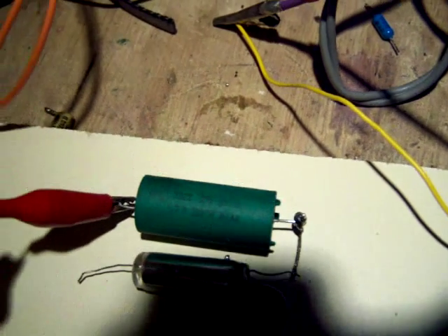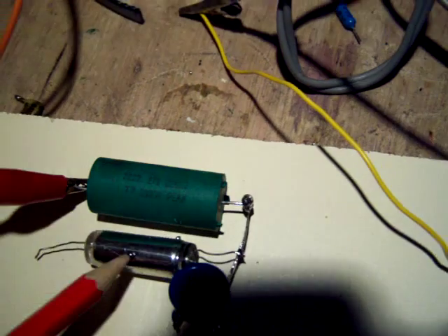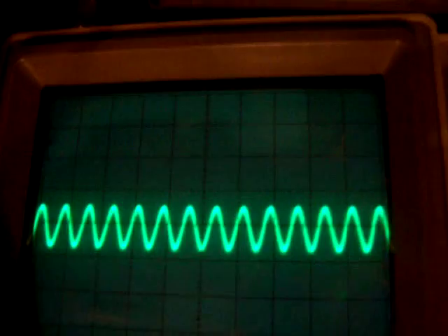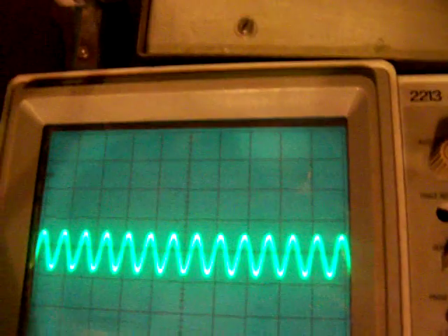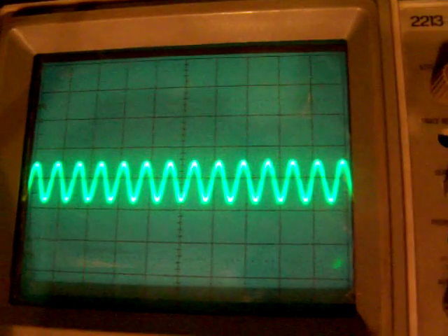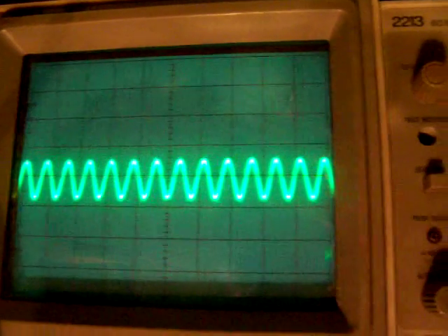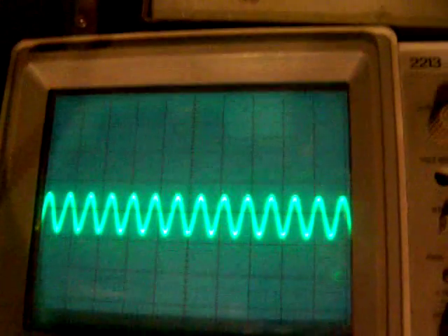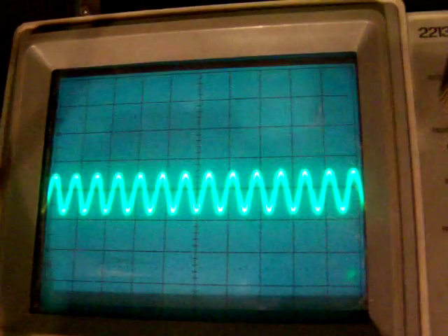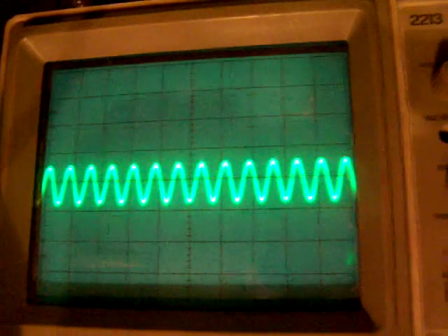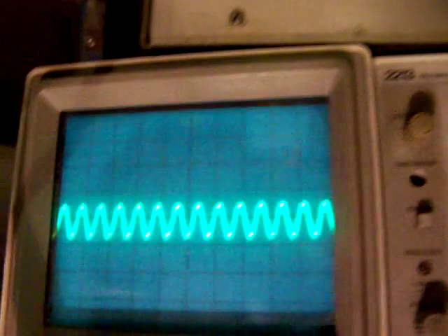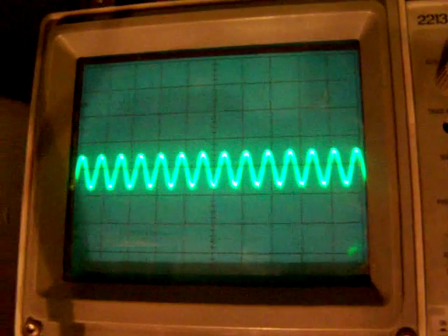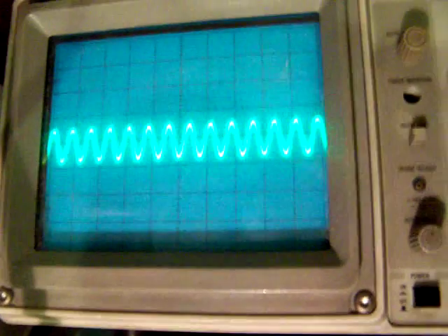Now I go with this frequency to the next capacitor, that's this one. The same frequency. Here we see the damping again. There's an enormous loss in volume, in level, from this at this frequency, and that's normal. We go to the blue multi-layer capacitor. Blue multi-layer. 10 nanofarad ceramic capacitor, the small yellow one, and finally a foil capacitor again.